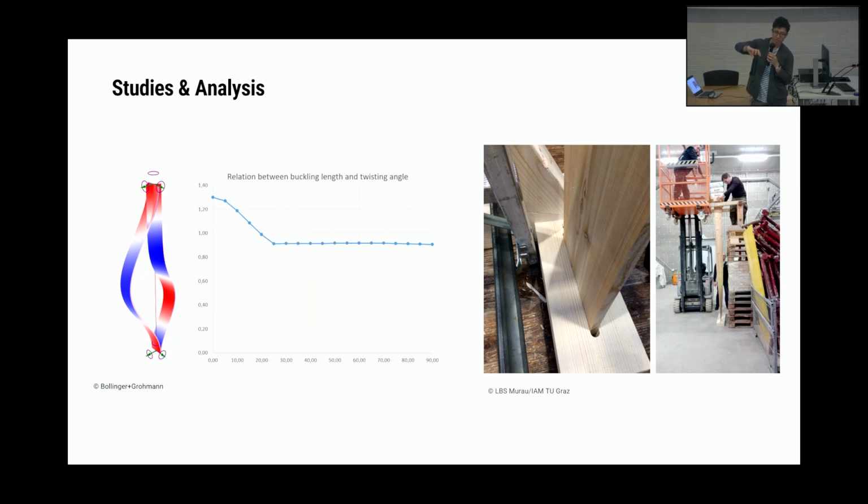When we start to rotate it, it adds some additional stiffness. And so the idea was to do this rotation that we could control in a sort of parametric way, so you have a gradient from this rotation, and looking at how this rotation could be used for structural stability. Initial studies in Karamba showed that approximately 30 degrees of rotation gave it much more buckling strength. And they also did some live one-to-one tests in the timber studio to assess this as well.